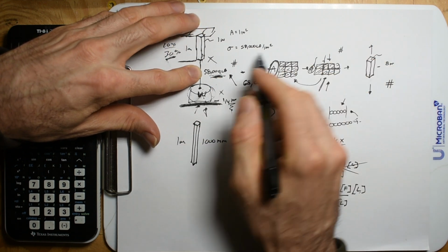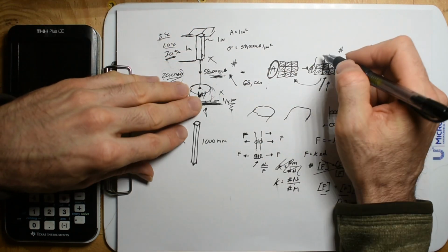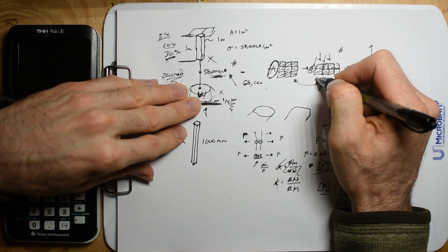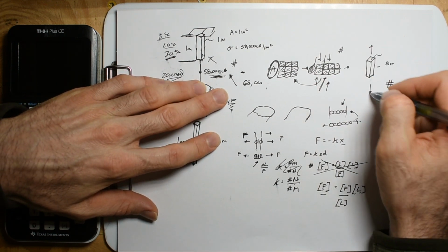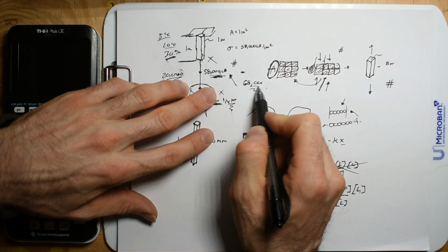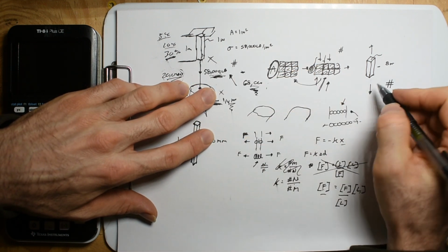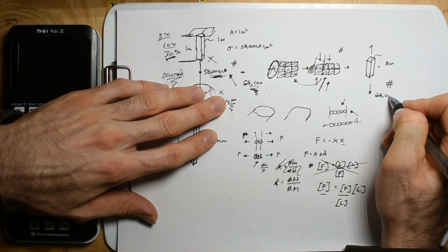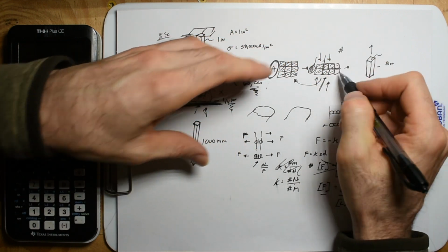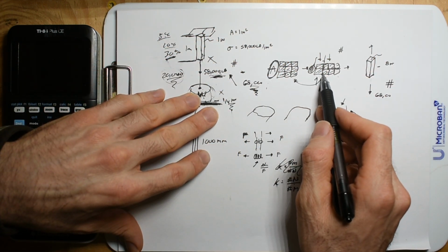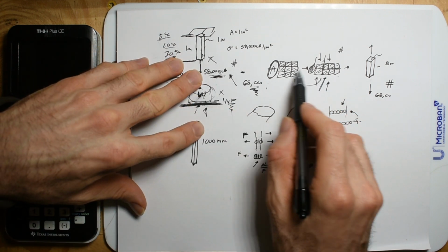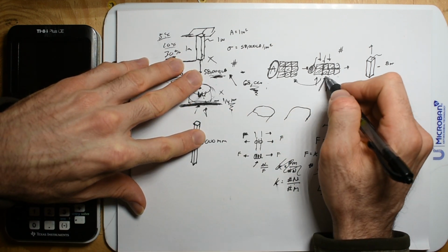As you're pulling 30%, this area is really reducing. We can actually increase the strength on our gauge. Now it takes 68,000 pounds to even keep moving it and keep stretching it. The second it starts to stretch, it doesn't require less; it requires more force to stretch that out.